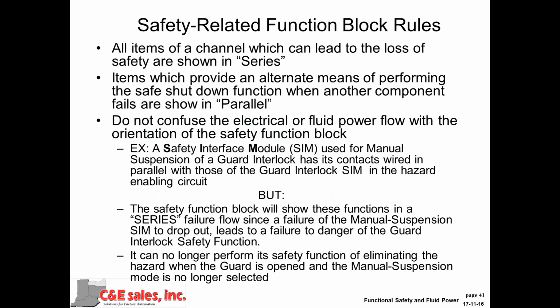For example, if I have a manual bypass or a muting module to bypass a door interlock under certain circumstances in manual operation, I would have the contacts of that manual bypass block or manual suspension block logic in parallel with the output of the door interlock monitoring function at the logic level.